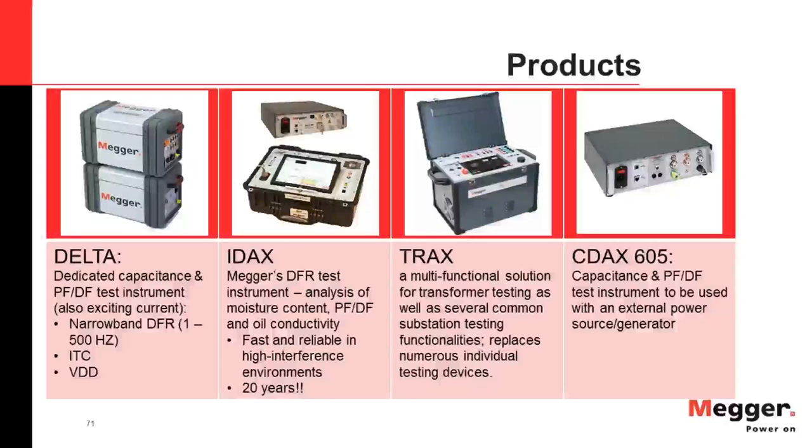All right, got another one for you, Jill. This person asked, did I understand that dielectric frequency response is a power factor test performed at multiple frequencies and may be a better indicator of moisture presence? And the answer to that is a resounding absolutely yes.